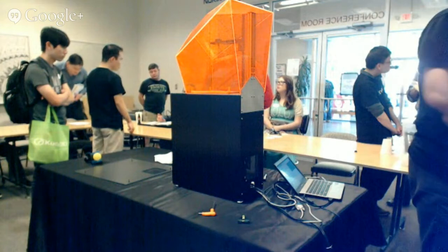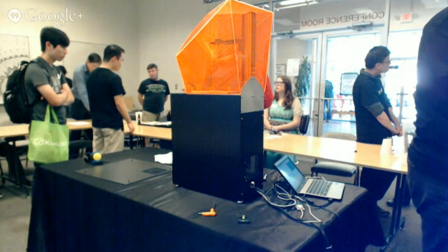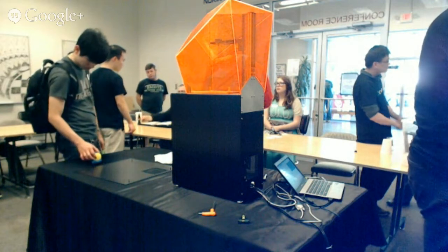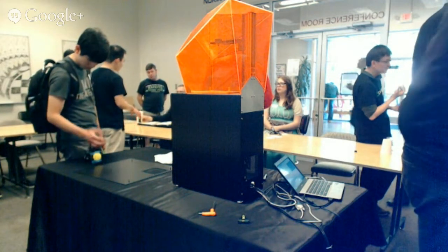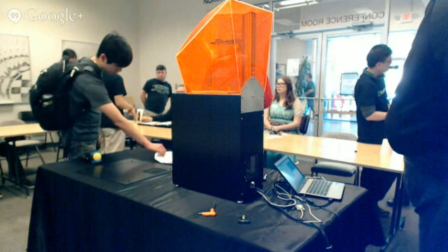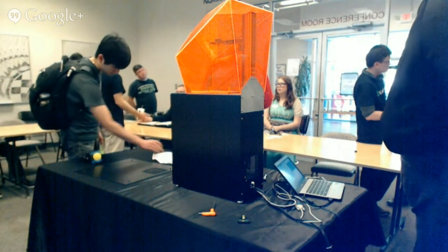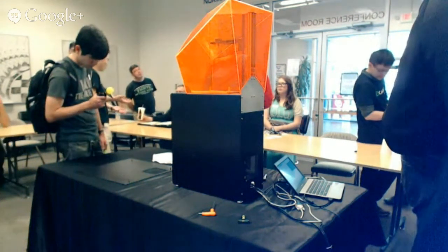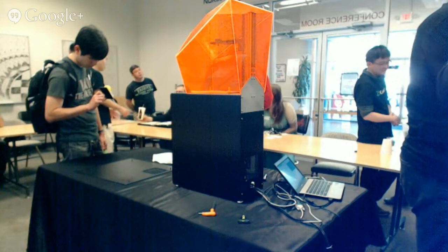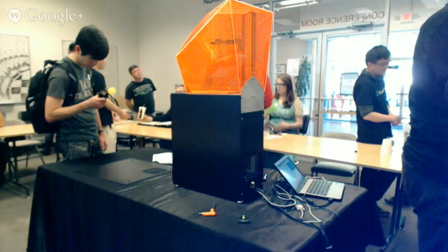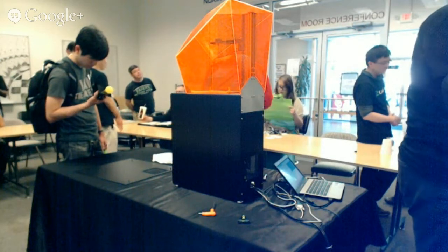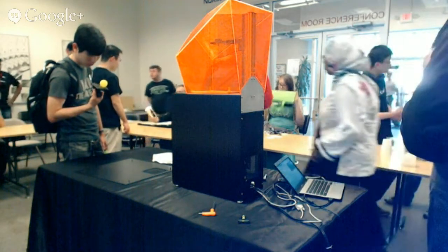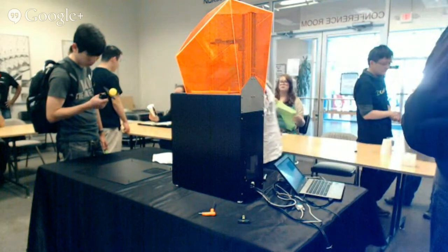And then the effective shrink also varies. Your handling will affect it a lot. For instance, ABS, from hot to cold, shrinks 10%. But you don't see these crazy 10% warped parts coming out of these MakerBot FDM printers. Generally, they look pretty good, right? Whether it's the models up front or the Starship over there. They don't look horribly warped, and that's because they're being held in position while they're being printed, and that resists shrinking.